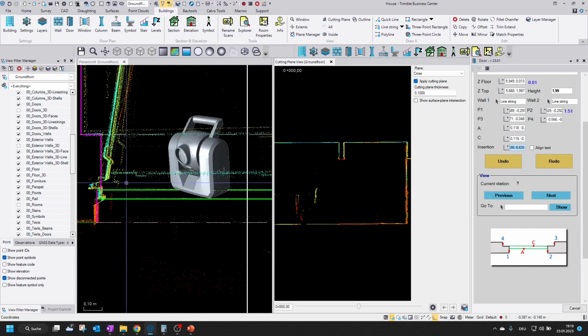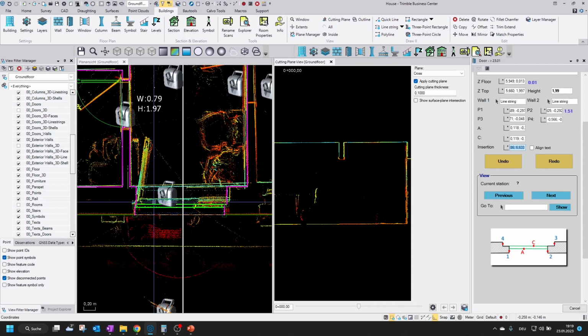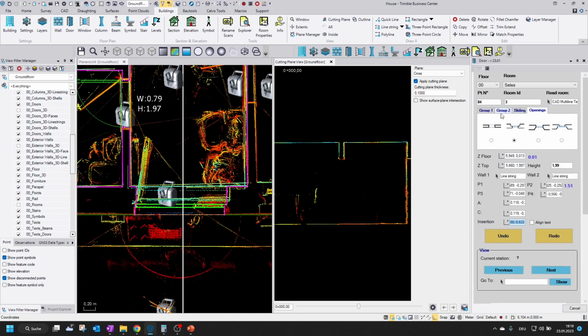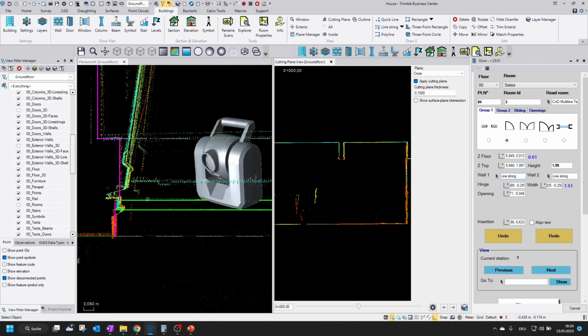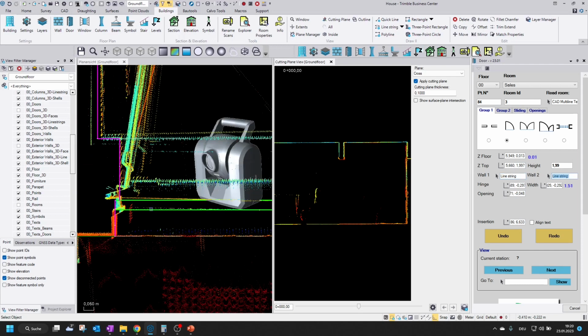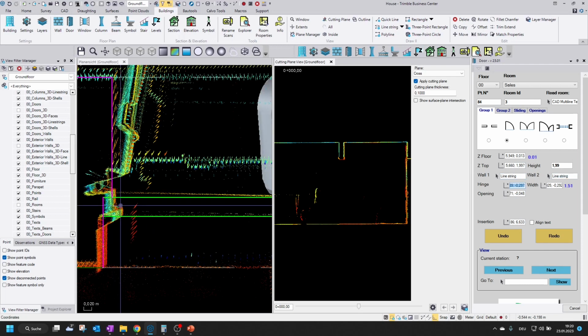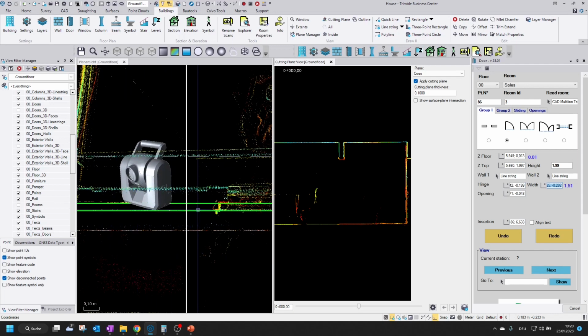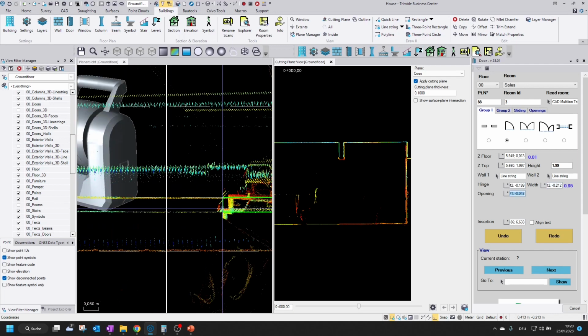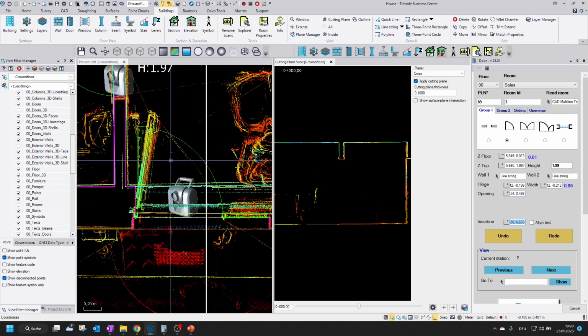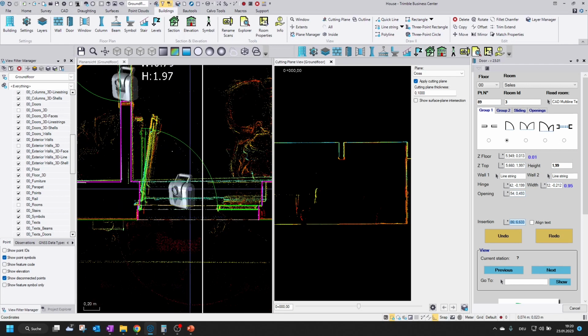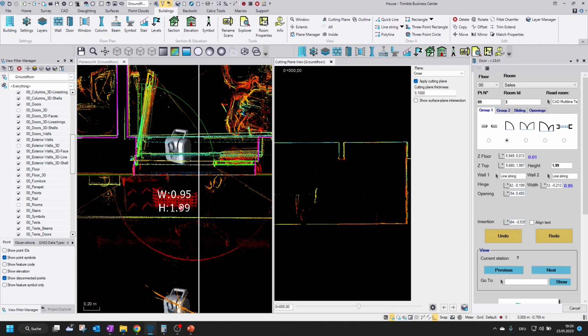So we have first this frame of the door, and now we can insert the door. Then we move to group 1, single door, because it's a single door here, and then we pick its opening direction. So first line, second line, hinge point, width point for the minimal clearing width. It's opening into this direction, and we insert the text there.